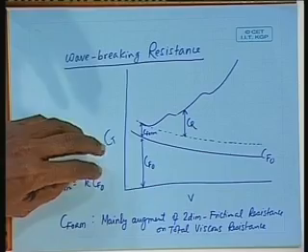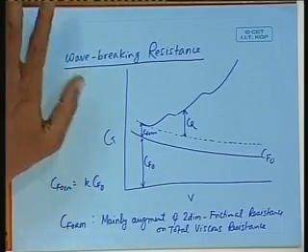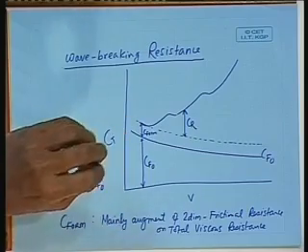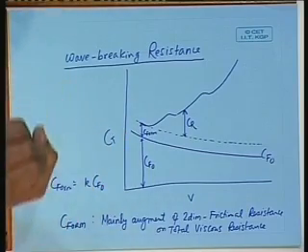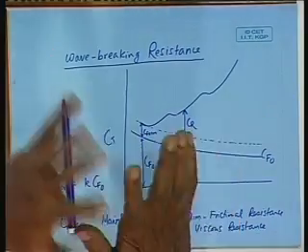Okay. So, we can say Cform includes the 3-dimensional friction form effect. It also includes some amount of separation drag component and viscous component. Imagine separation, we have said, is related to velocity and pressure. They will change with velocity of the ship. So, if it is something at low speed, it cannot be the same at high speed. So, truly speaking, we have not taken this totally into account. That is why I am saying mainly. The word mainly is important there, it is not total.